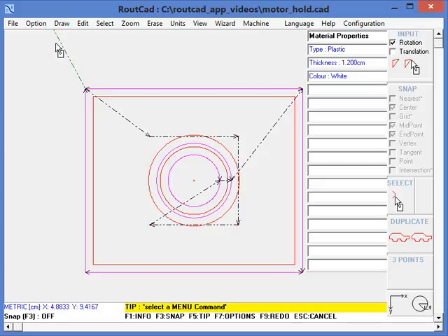By displaying the route arrow, now we see the actual sequence and direction of the machining. The first line in red, that is dashed, is going from the origin or home of the CNC, the 0,0, and goes to the first point to be routed on the part. In this case, we made a point at the intersection of those two lines, and if we place the mouse on it and click the middle mouse button, we get the properties about that point.